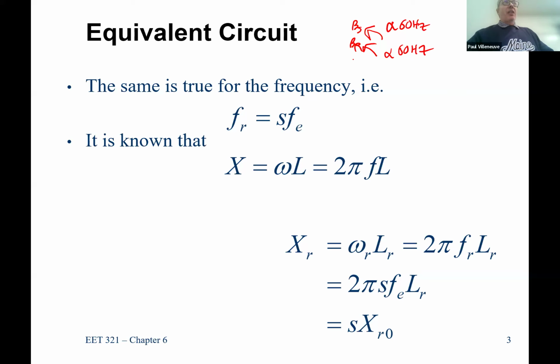Well, in this case, under locked rotor conditions, that's at 0. So shouldn't it be operating at 60 hertz? If it has to be at the same synchronous speed and that rotor is not rotating at all, but the rotor has to make up the difference between what the rotor field is operating at and the synchronous speed, then it has to be 60 hertz. Okay? So it is important to see that the electrical frequency on the rotor is going to be the difference between synchronous speed and actual mechanical rotational speed.